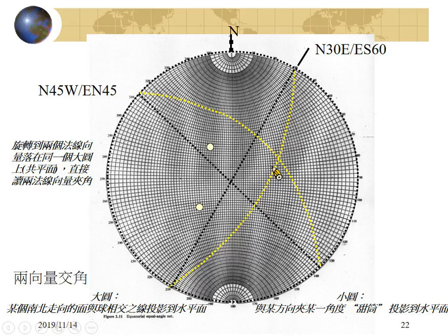Okay, if you want to determine the angle between two planes, the same, you were trying to get the normal first. And you were trying to put these two normal vectors on the same great circle. Put on the same great circle. And count in the small circle. Small circle will be the angle, right, between any directions. So if you put these normals on a single plane and calculate the angle, that will be the answer. Is it okay for you?